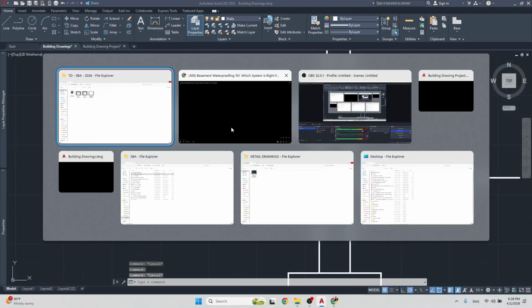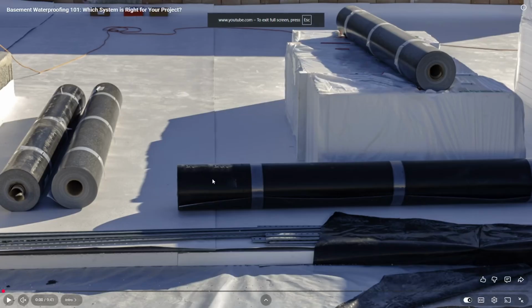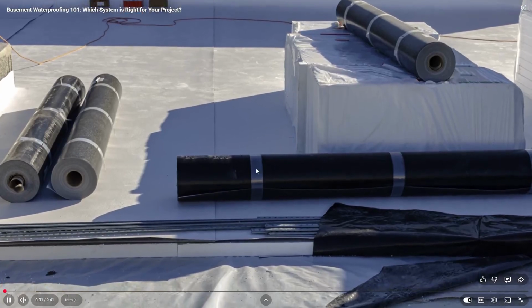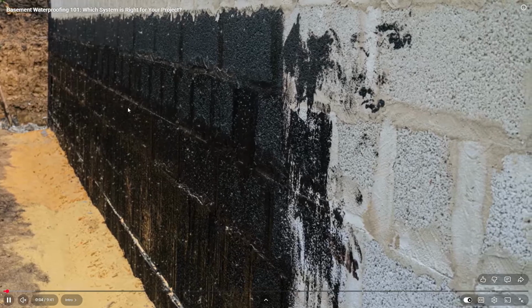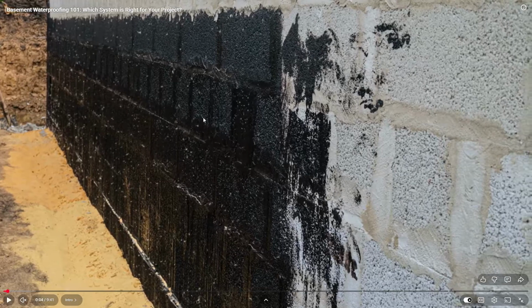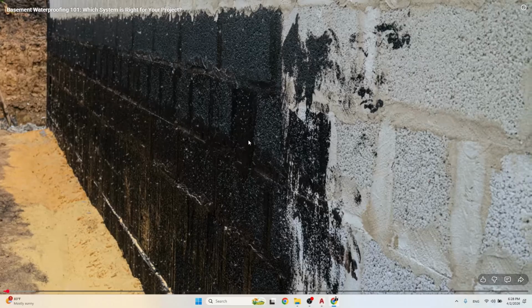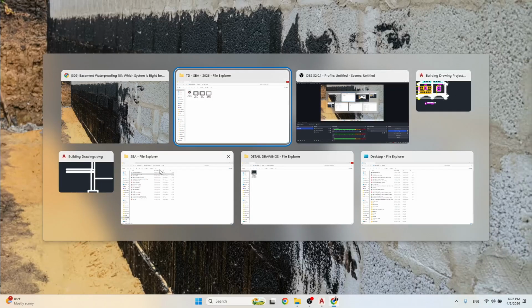What is damp proofing, you might ask? Well, damp proofing could be polyurethane, it could be a bituminous material membrane. So it could be like a plastic material which you roll out and then you kind of torch it to let it turn into a seal. It prevents moisture from coming up from the earth through the floors. It could be plastic like this that you roll out, or it could be like a liquid that you paste on, and then it will cure into that seal. All right, that's all I need to talk about for that.